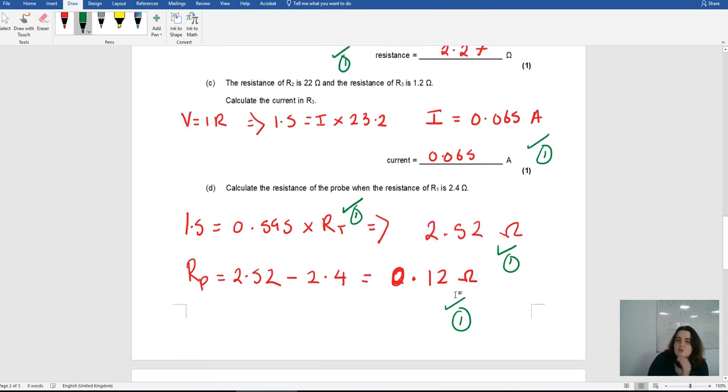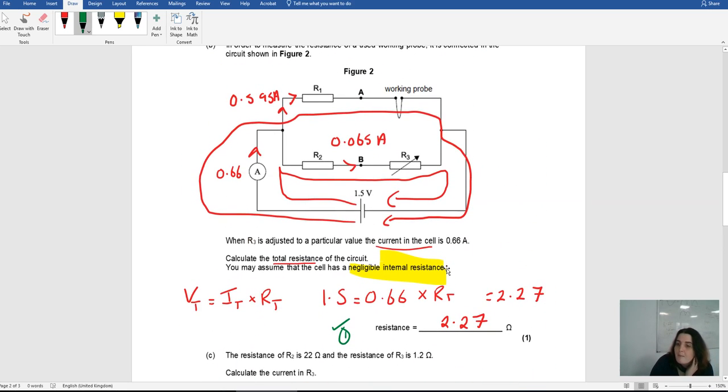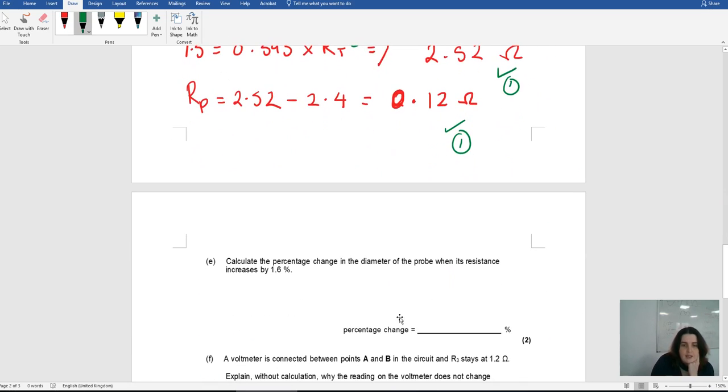So draw all over your circuits. Remember things like Kirchhoff's voltage law, that if I'm doing a loop around, I'm going to lose that potential. So I know I'm going to lose 1 volt of potential in this path and in this path, in total. And I know that when current goes into a node, the current leaving the node is exactly the same that went in.